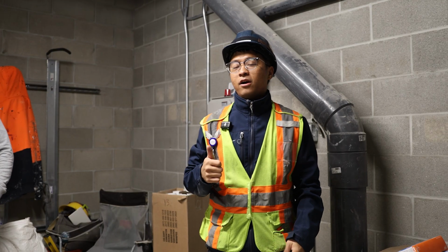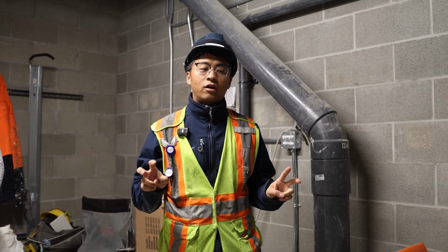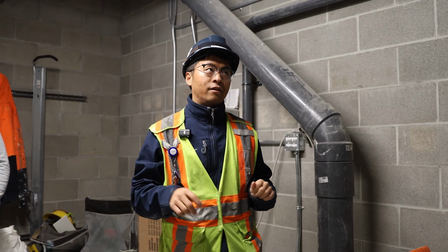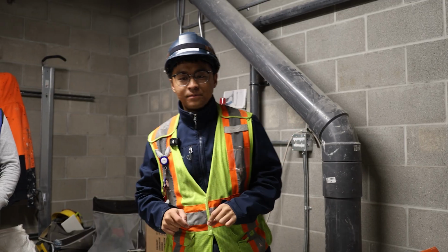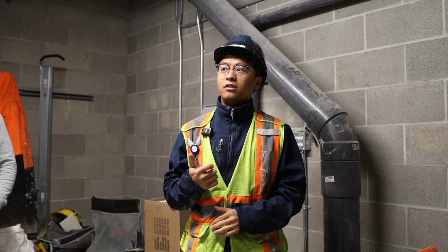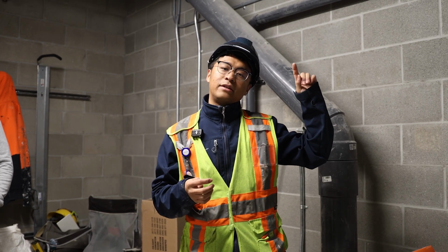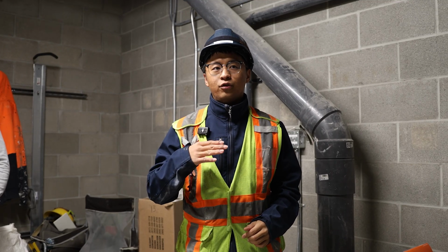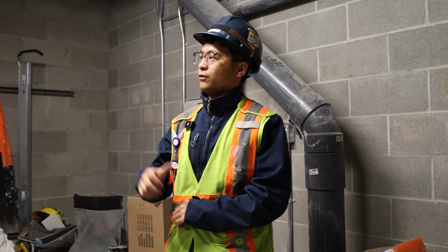So this MUA only turns on when the dryer is on. So the BMS monitors the dryer status in two rooms, one on the west side, the other one on the east side, I believe. Yeah, so BMS only turns on the MUA when the dryer is on. And BMS also monitors the mixer damper. The mixer damper modulates to maintain the space at neutral pressure. Do you have any questions for the MUA?